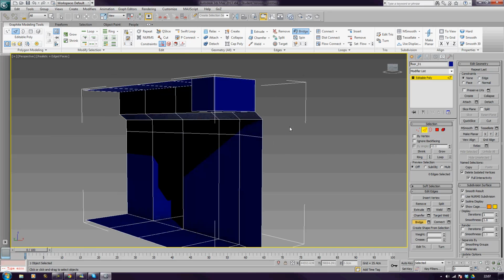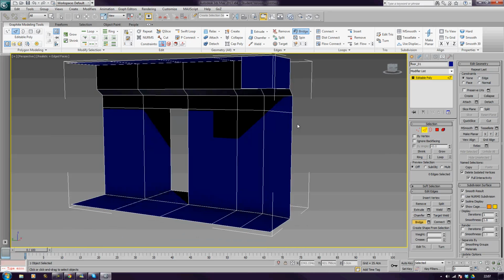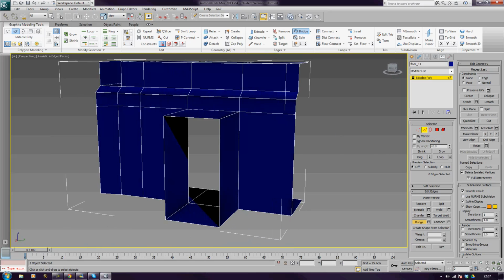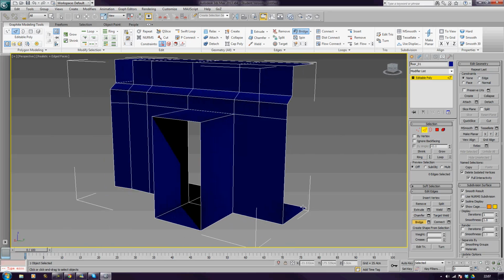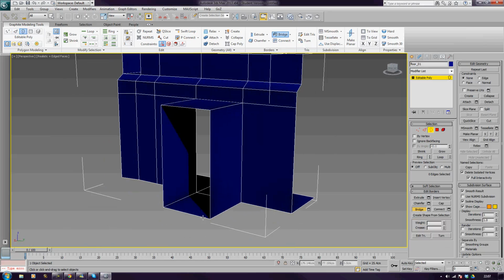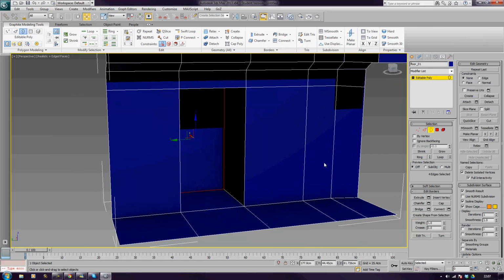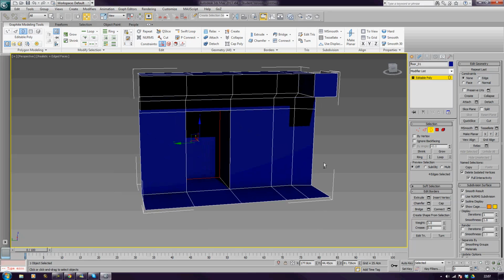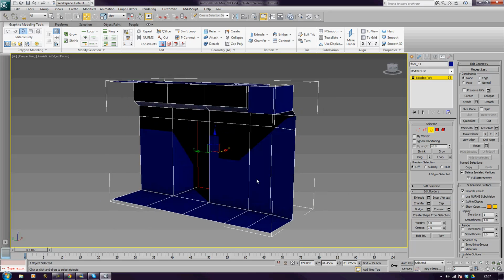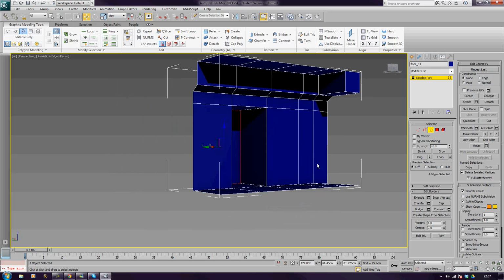Okay, so now what I want to do is close off this area of the corridor. So I'm basically going to put a cap on the end of this, and then we can just put a simple door on it later. So there it is, and I'm going to click cap like so. As you see, it's set quite far back, that's fine. I don't need to create a door frame as I'm just going for quite a low detail here. However, I probably should anyway, I suppose.